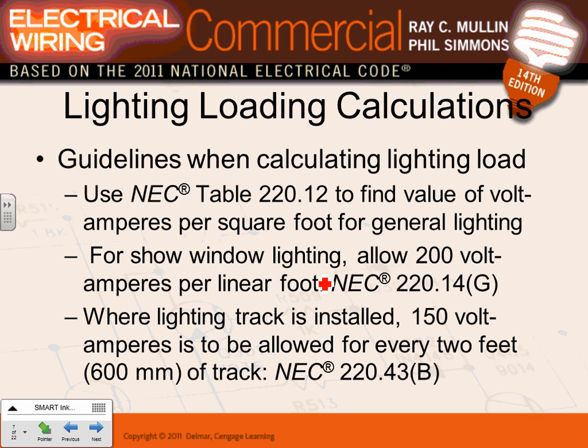Okay, so everybody has been there in Table 220.12, guys. That gives you the volt-amperes per square foot. In a commercial building, we say 3 volt-amperes per square foot. We talked about show windows. You guys remember that show window? You allocated 200 volt-amperes per linear foot, right?